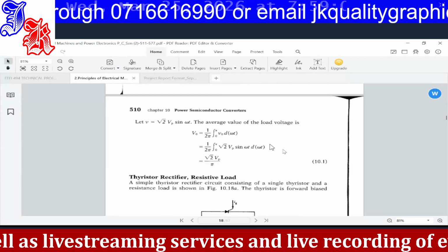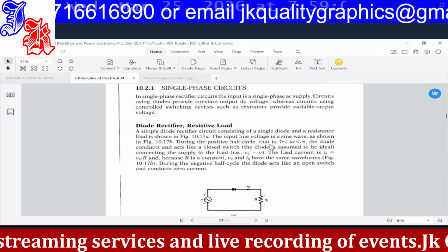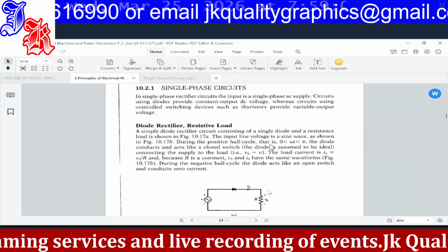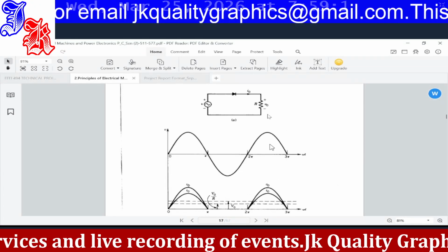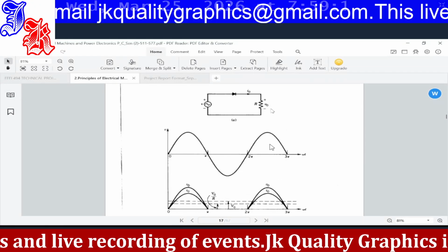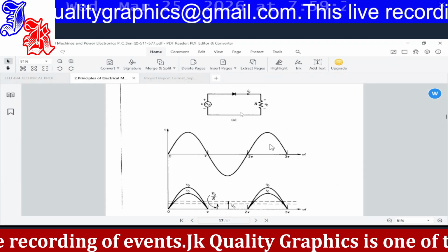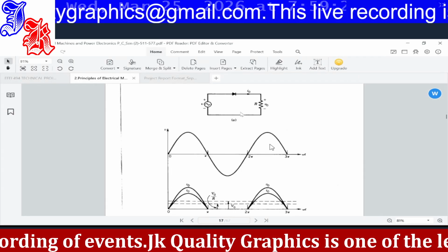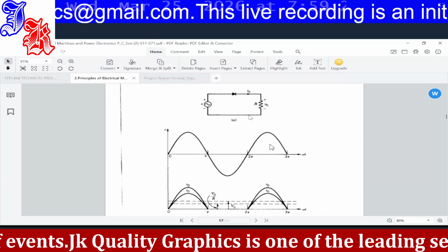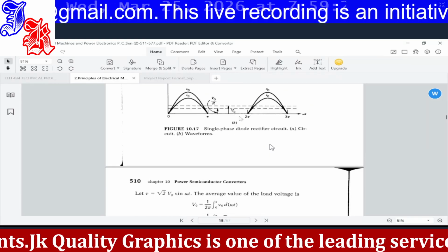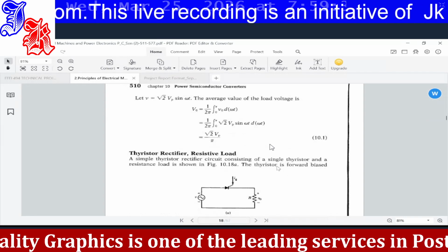So before we go there, maybe you will find your own time and consider that now we have two diodes. Both the positive and the negative get to reach the load. So you will draw the same circuit, but now with two forward biased diodes that allow both the positive and the reverse to pass, and see how this wave will look, and how this calculation will look.